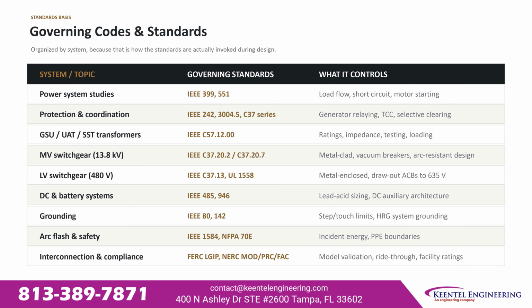The standards basis is organized by system. Power system studies follow IEEE 399 and 551: load flow, short circuit, motor starting. Protection and coordination follows IEEE 242, 3004.5, and the C37 series. Transformer design follows C57.12.00. Medium voltage switchgear follows